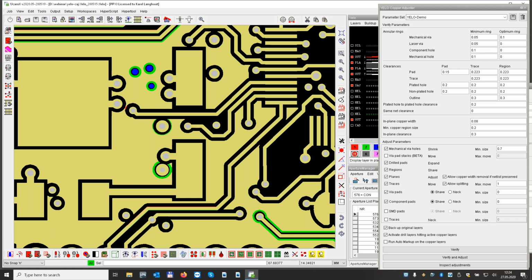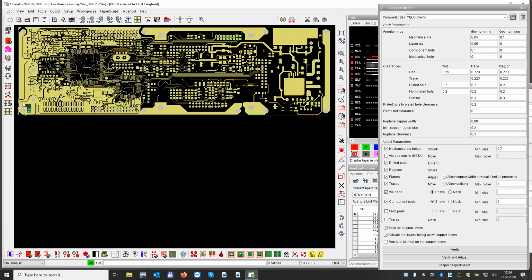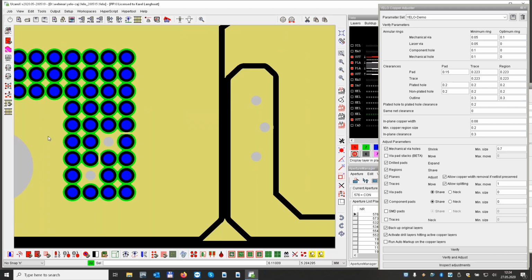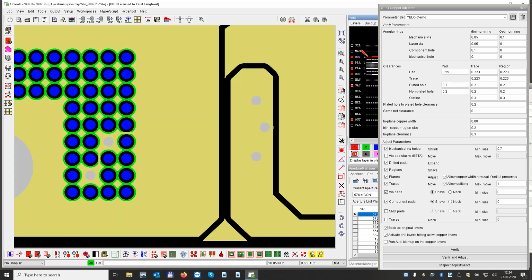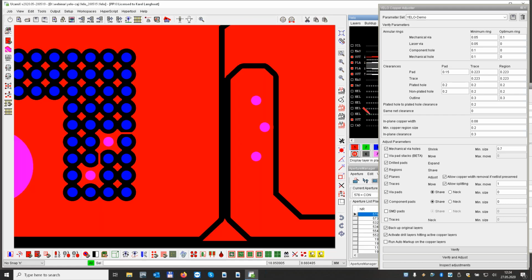Then we are getting to an interesting part of the PCB. You can see the green layer. I will maybe hide the red. This was the original, the green layer. You see that the clearance around all the pads is not nearly enough. I want to have 0.3, and I think this is about 0.1 or 0.15. And what we made out of this is this. I will hide the green layer now. So it looks quite different.